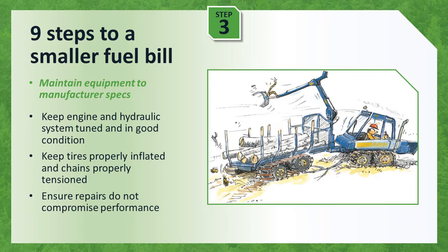in the hydraulic system. Lastly, if repairs have been made to the hydraulic system in an expedited manner, ensure that the new hoses and fittings are of the correct size and length. Remember, constrictions in the hydraulic system create excess heat, which wastes fuel.